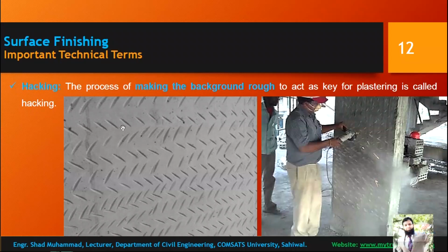To make the bonding of the mortar with the surface enough so that they adhere to the surface, we need to have hacking of the surface.